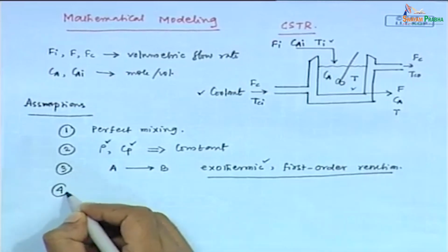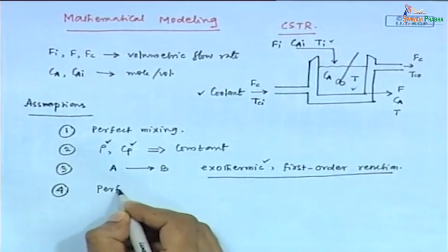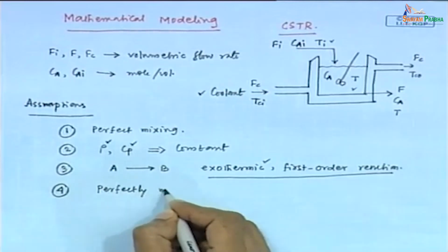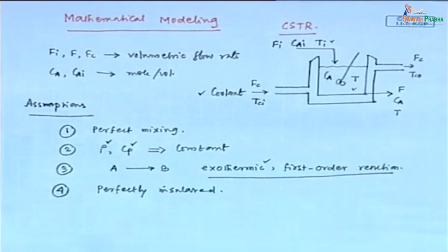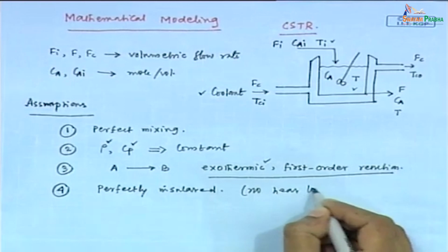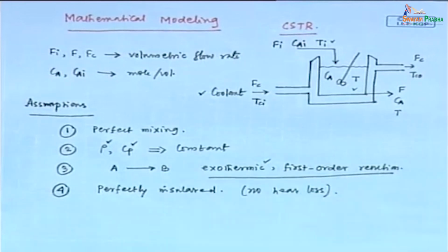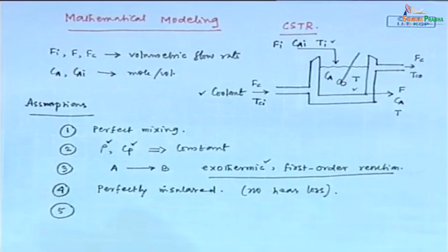Fourth assumption is the reactor is perfectly insulated. That means there is no heat loss from the system to the surroundings. Fifth one is the coolant is perfectly mixed in the jacket.